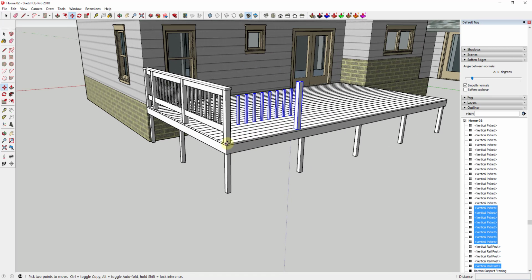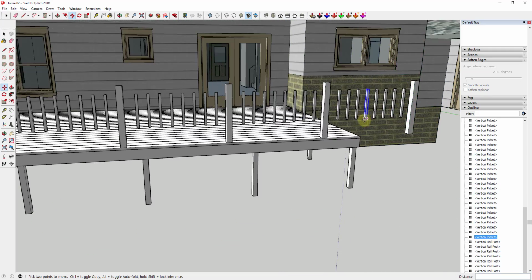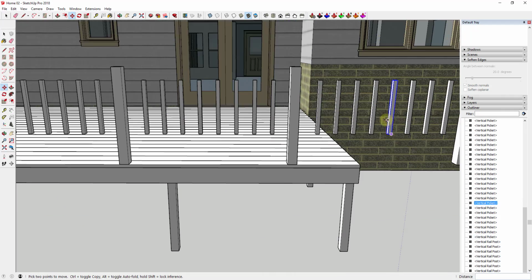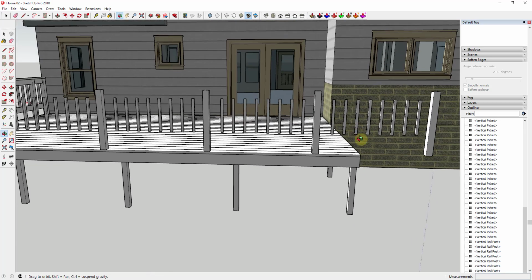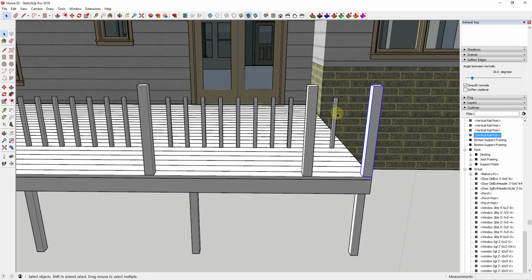And then we can use the move tool in copy mode again in order to copy that across. So I could type in ×4. And you can see how, again, we get some kind of weird spacing on this end. There's 2 ways that you could do that. You could either make these longer on the end here, or you could do what I'm going to do, and you could just erase out these extra pieces. Whoops, and not my house. And then just move this piece back.